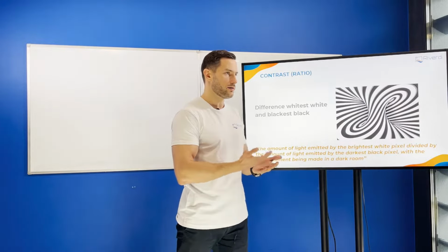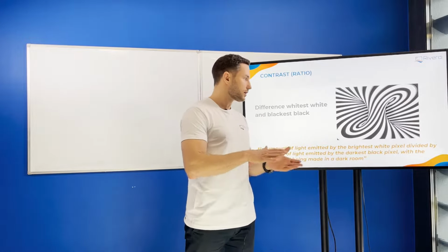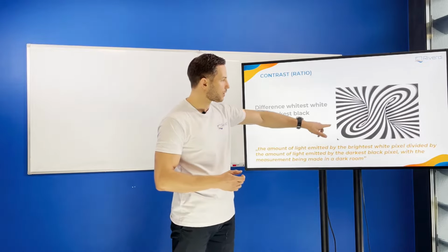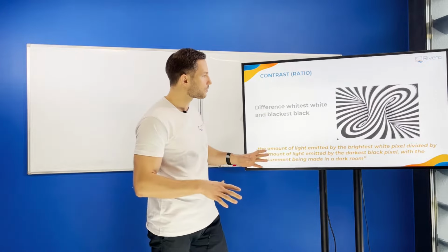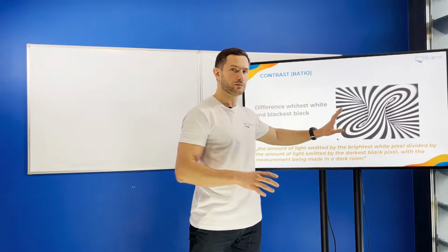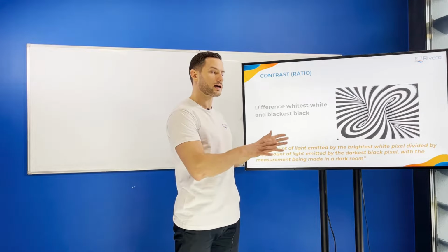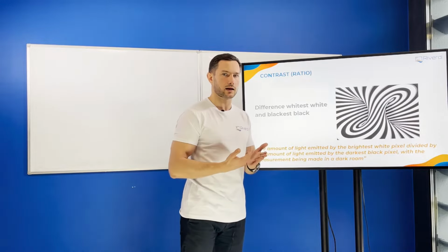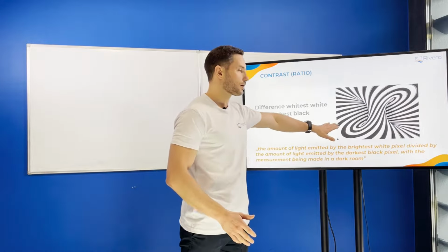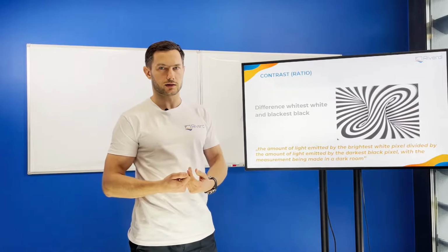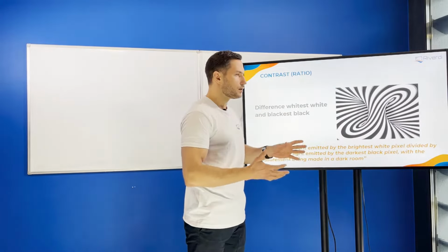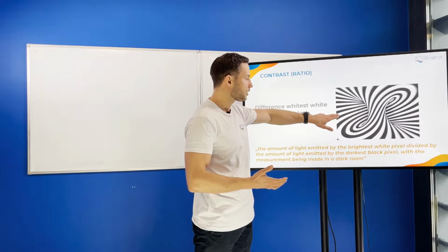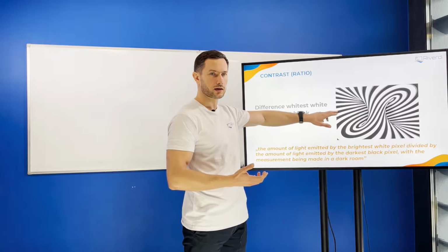And then, having the backlight on and the pixels blocked, that is the black color here, we will measure the brightness, because some brightness is here, of course. If we, for example, make the display entirely black but don't switch off the backlight, we will see that there is still some light coming out of it, because the pixels are not perfect, they are not perfectly blocking the light. So maybe we have 1,000 candela here and maybe 10 candela here, yes?